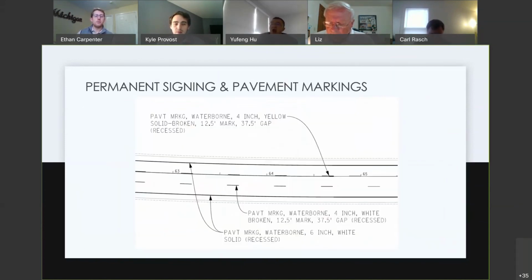All pavement markings were designed according to specified passing lanes. Since there are no passing zones to the west of the bridge, the length of the center line between lanes were painted a 4-inch yellow double solid marking. East of the bridge, however, required a 4-inch yellow solid broken and a 4-inch white broken pavement markings to indicate the truck passing zone when climbing the hill.